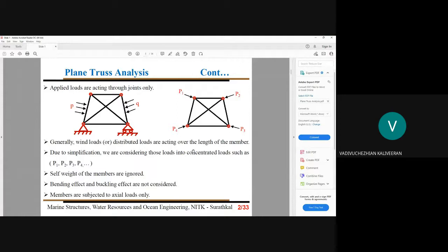So when you think about compression and tension, obviously the axial stiffness part we have to consider, and the axial displacement. What is our corresponding effect? That is displacement only. When we apply load, obviously it will be extended or contracted. So those portions are involved in our compatibility part when you think about a statically indeterminate structure.